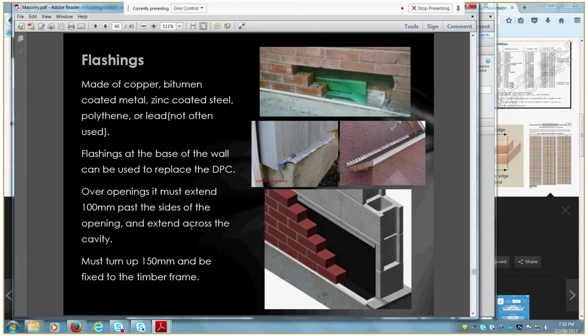And that's carried back to our stud work, and then in elevation view, that's our window here, we carry our flashing 100 millimeters past the edge of the window, because we want to ensure that any bits of moisture that land here and get blown inside don't go inside the wall. They'll travel back out again, or any moisture coming down the inside face. Carried out.